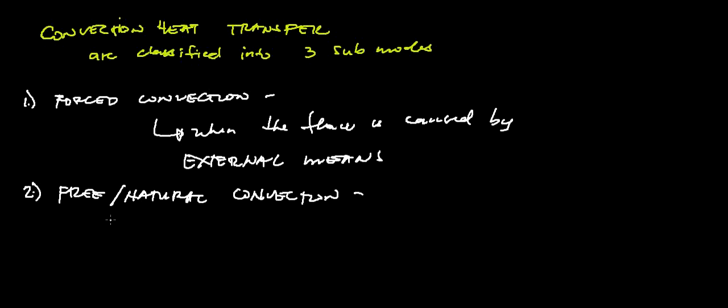It is when the flow is induced by buoyancy forces. What happens there is usually density differences caused by the temperature variation of the fluid, right? So examples are the evaporators and condensers of the household refrigerator, the radiator and convectors for space heating, heat loss and heat gain of connecting ducts, and so on.